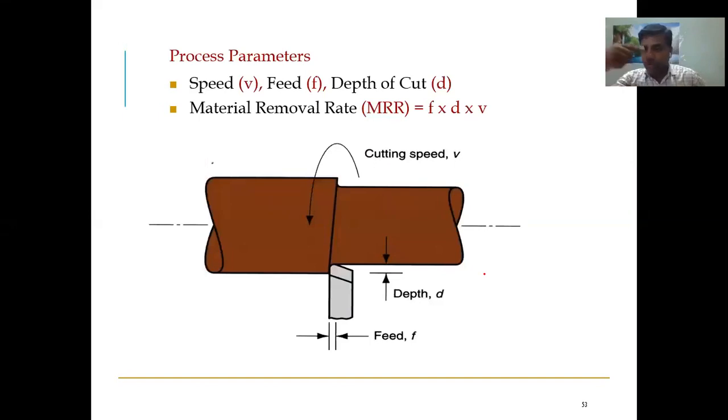एक wheel का जो circumference है वो 60 बार revolve हो रहा है 1 second में. So whatever the circumference of your tire is, you need to multiply it with the number of turns. That will give you the velocity or speed at which your vehicle is moving or your wheel is turning, right? अगर 60 turns 1 second में कर रहा है और उसका diameter आधा मीटर है, so how will you calculate the speed of the wheel? Simple, pi d n by 60.